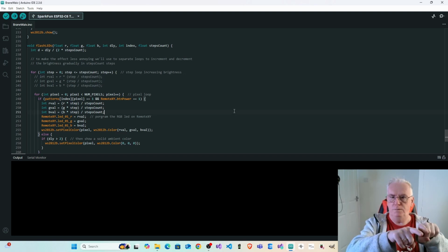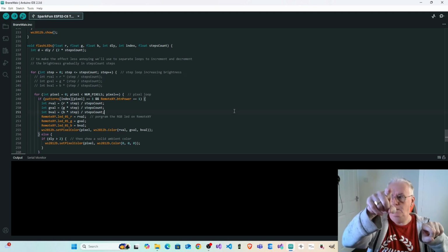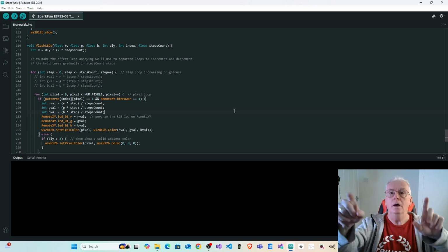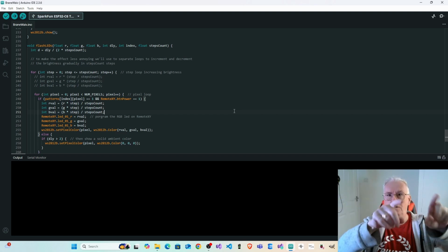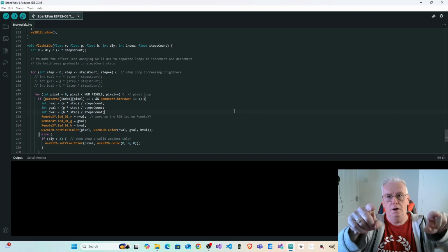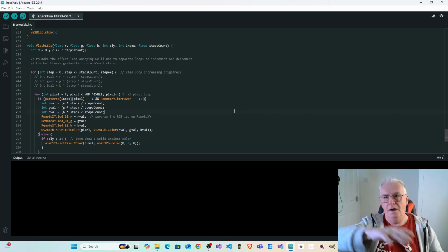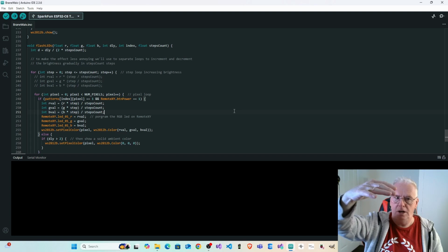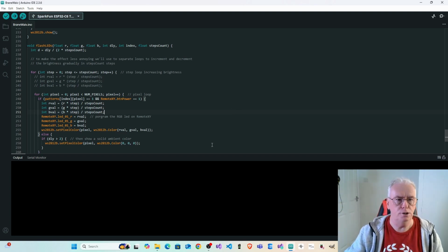And I step it from 0 to 10, where 10 is the max. I then used that as a multiplier: multiply the maximum value 255 by the value and divide it by 10, and that will step up and increase it. So 10 is maximum illumination, 0 is no illumination. And I do it for R, G and B values. And I'll learn to program.